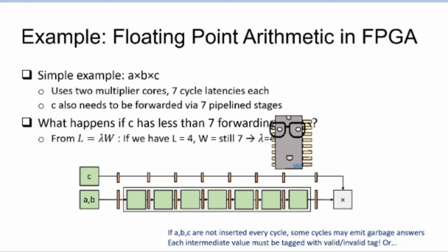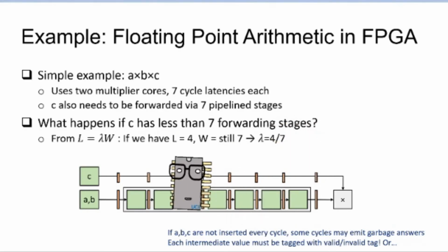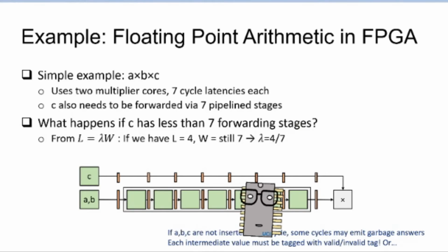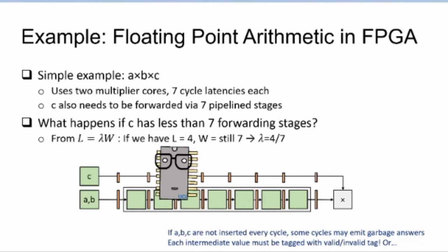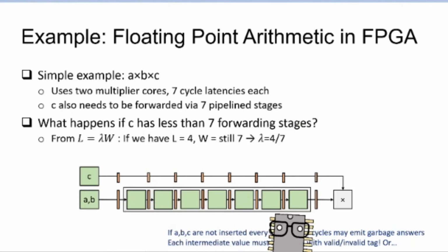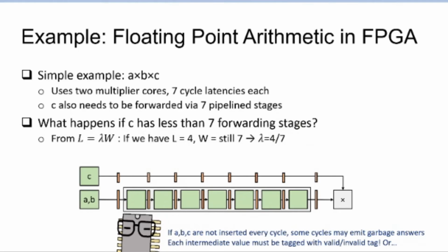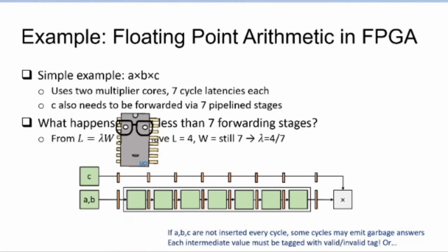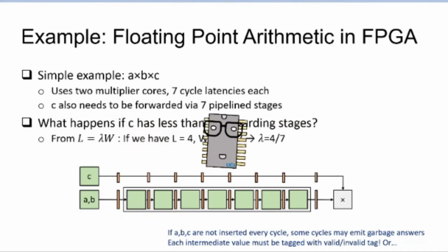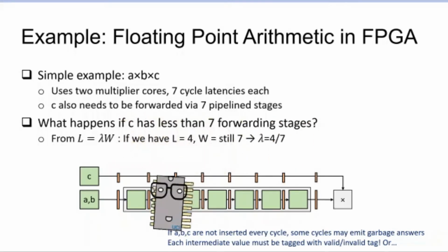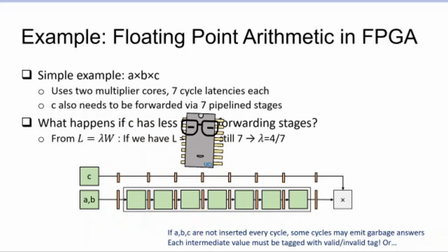That implementation will be correct, but the performance will suffer if the pipeline stages here are mismatched, because the total number of elements we can have processing at any given cycle is only 4, even though this pipelined implementation of the multiplier can have 7 multiplications operating in parallel at different stages of the pipeline. If the number of pipeline stages on this side is only 4, then the circuit will block after filling in these 4 registers.